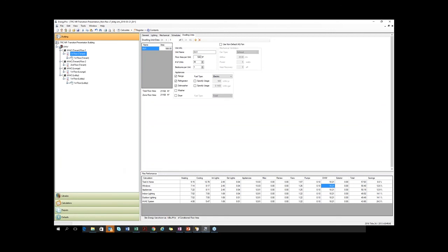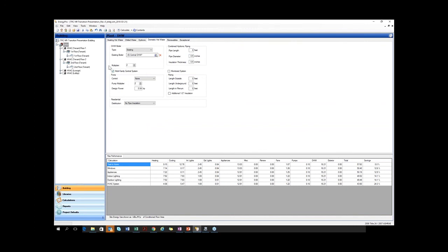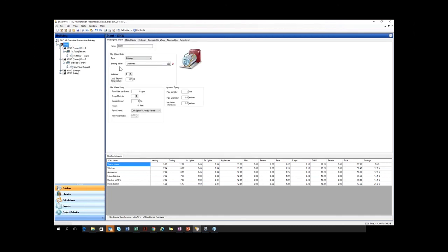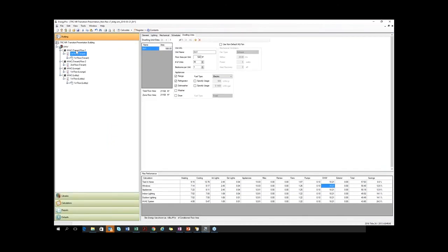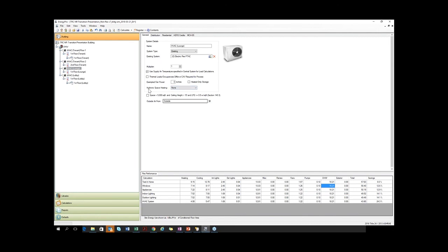In EnergyPro version 5, you define your domestic hot water system, and say you have hydronic heating, you would just come into the HVAC, define hydronic, and if you didn't define a boiler in heating hot water, it would automatically draw that water from your DHW. In EnergyPro 7, that's not the case. You either need to replicate that DHW boiler, just copy it and do the same thing right here, or you can come down to the HVAC system and there's an item right here, hydronic space heating, select DHW boiler provides heat. So you just need to specify that additional item.